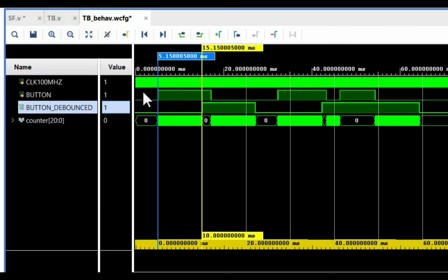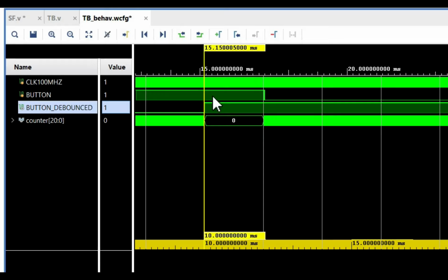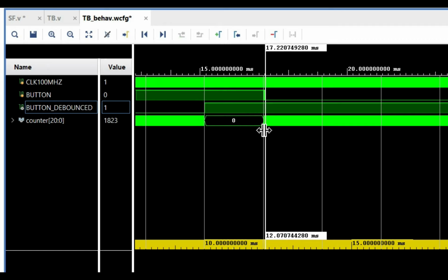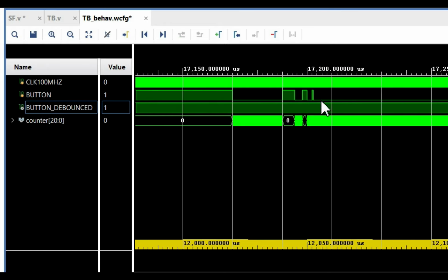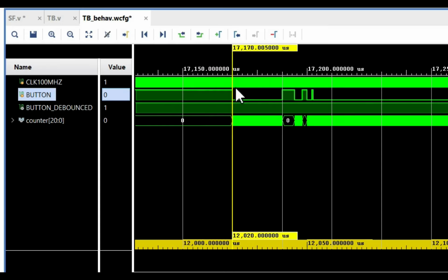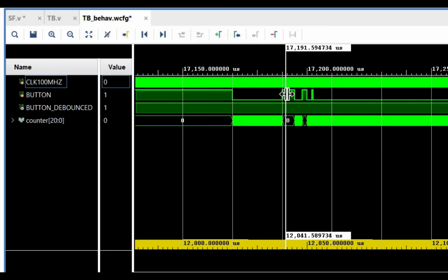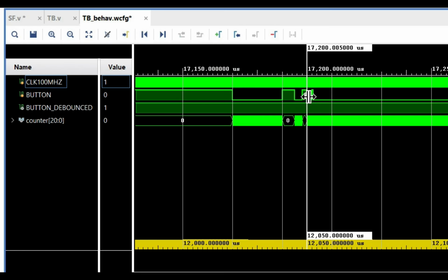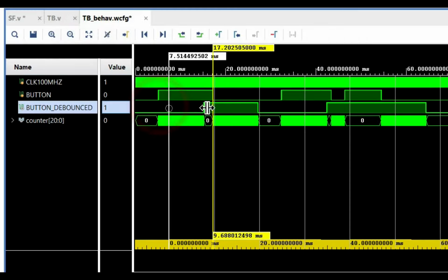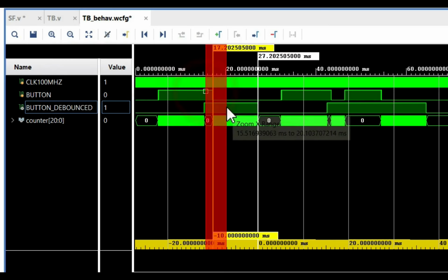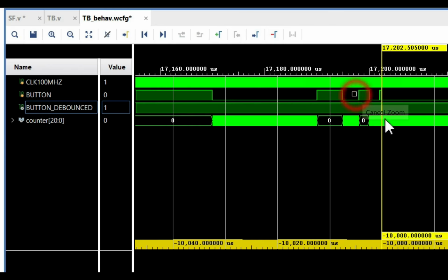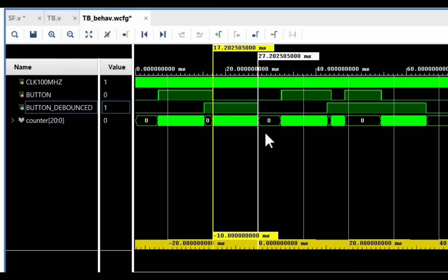So then, once that happens, the counter, now that the two inputs are equal, it's just resetting to 0 because line 52 is just executing indefinitely. Then finally, when the button is released, here it seems like it's released for good, but oh, nope, it's not. So then it goes back up, so it resets to 0, then jitters again, until finally here it stabilizes. So then if we go there, we get this. Then 10 milliseconds after the actual final last edge, it transitions back to 0.